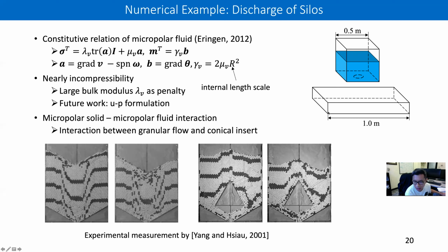In this particular case, we can clearly see that the size effect is very important. Imagine that if we try to discharge particles that are bigger than the hole, jamming would occur. But even without the jamming, the size of the particle would definitely affect the discharge rate. And this could not be described in classical continuum mechanics, at least not easily.